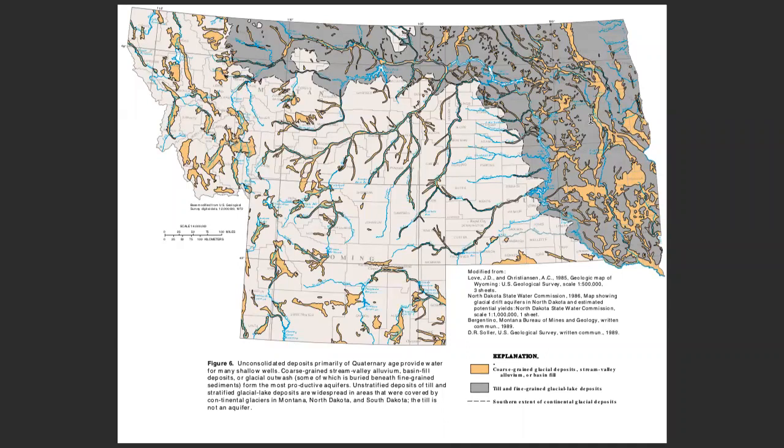And the first and most fundamental thing you should take away from this class is that every river system has an alluvial groundwater system associated with it, and they are completely tied together. So you can't have a river without an alluvial groundwater system. It will dry up. You can't have one without the other. And every river, when you roll up on a river, know that there is a groundwater system of some varying size around that river system, and that the groundwater and the river are talking to each other all the time.